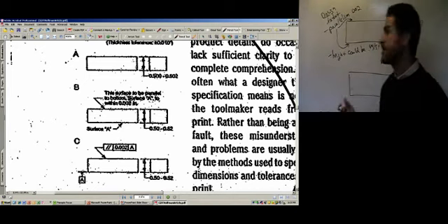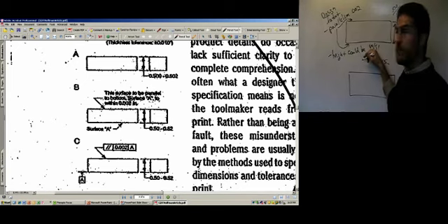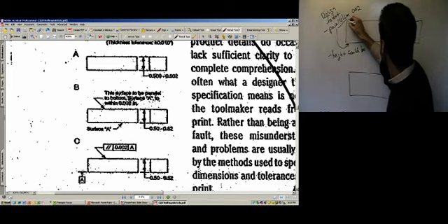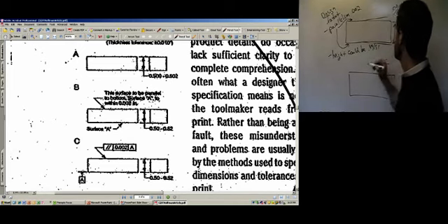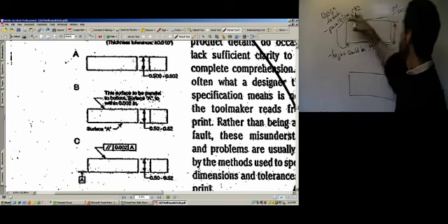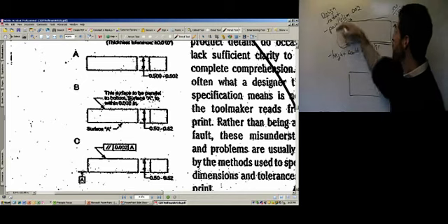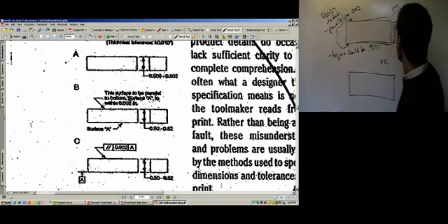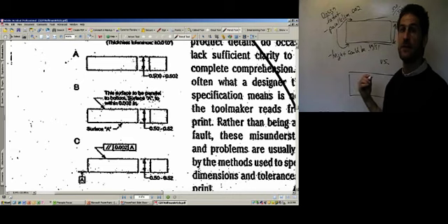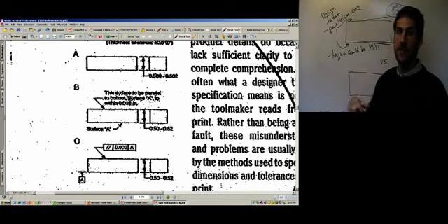Of course, the designer doesn't want to put that as the tolerance there, because then we could end up with something that's basically not parallel, where it's 0.49 at one end and 0.51 at the other, and then it wouldn't be within this .002 parallel. So the designer here doesn't really know how to put both of these requirements in with just a coordinate dimension. So they figure, well, I'll just put in this, and that'll make sure that the top and bottom are parallel within 2 thousandths.